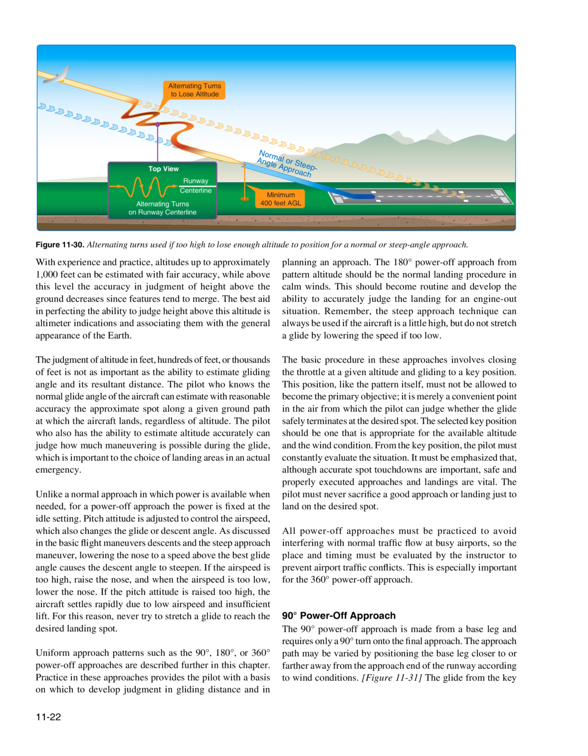If the airspeed is too high, raise the nose, and when the airspeed is too low, lower the nose. If the pitch attitude is raised too high, the aircraft settles rapidly due to low airspeed and insufficient lift. For this reason, never try to stretch a glide to reach the desired landing spot.